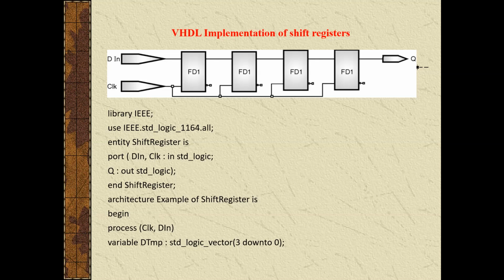So let's see how to declare the port here. What are the inputs here? The clock is necessary for synchronizing the operation, and the serial output data and DIN are given here. Synchronous and asynchronous parallel load is also there, and a clock enable signal is also there, and serial or parallel output. These are things generally used in the shift register.